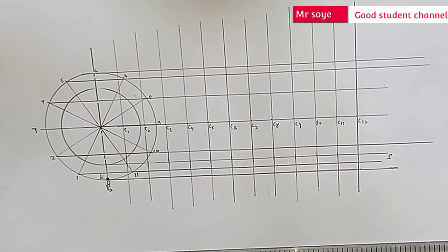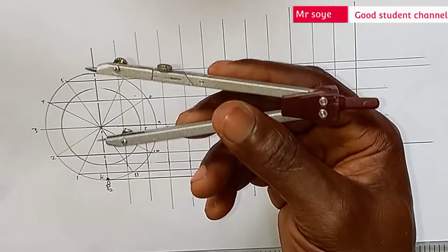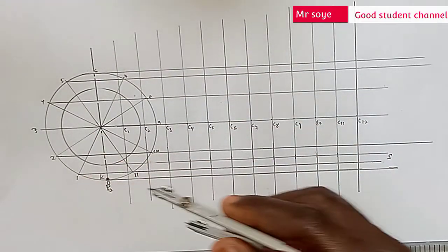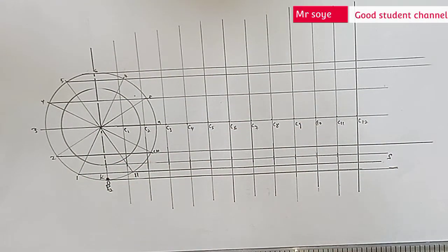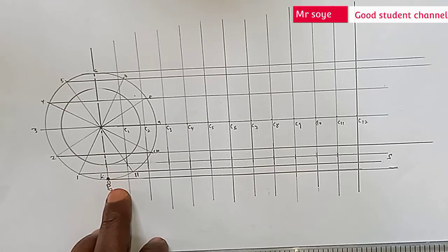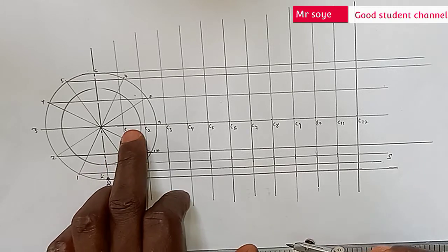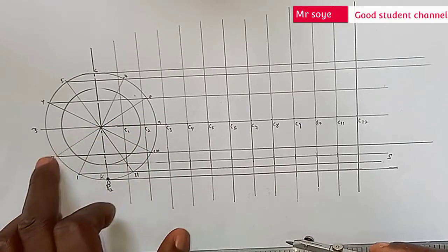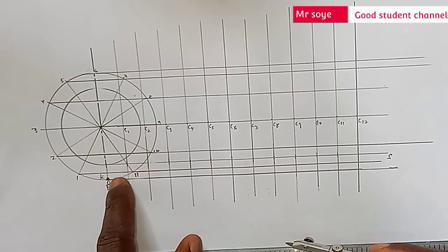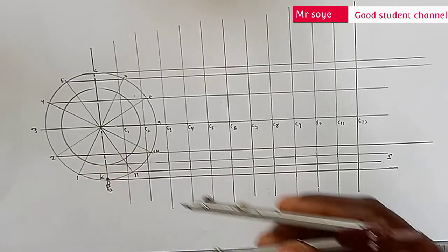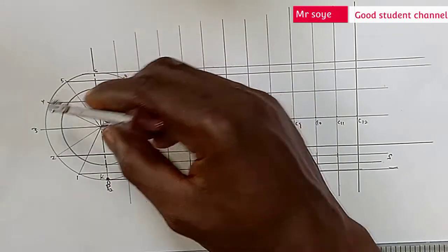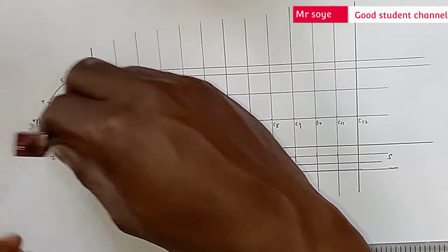So now, after taking your compass to the radius of the generating cycle, the one that generates the point here, it has generated the point at 0. Now we'll take it to center 1 with the radius of the generating cycle. Mark line 1. So that's another point. Now let me confirm this again. Okay.